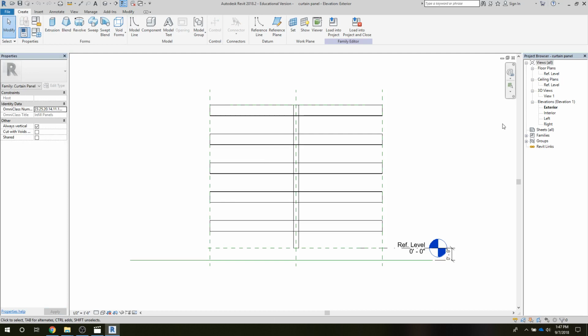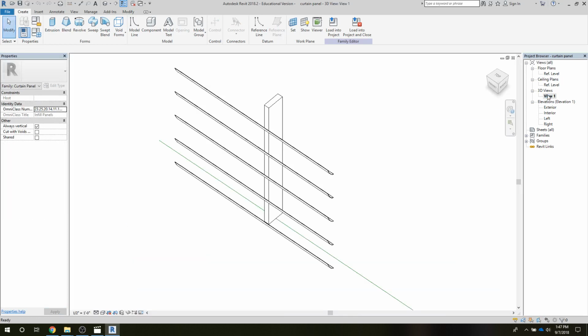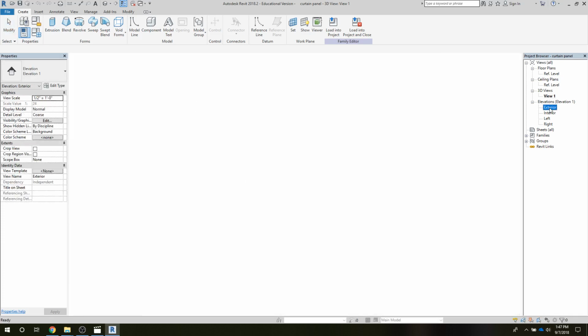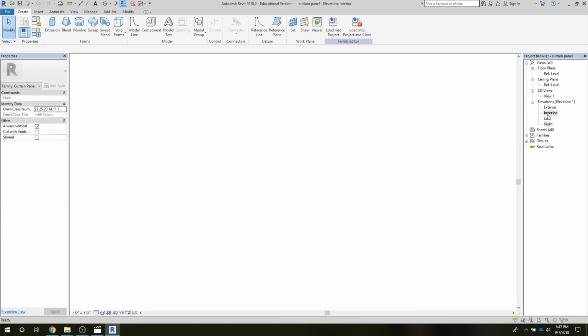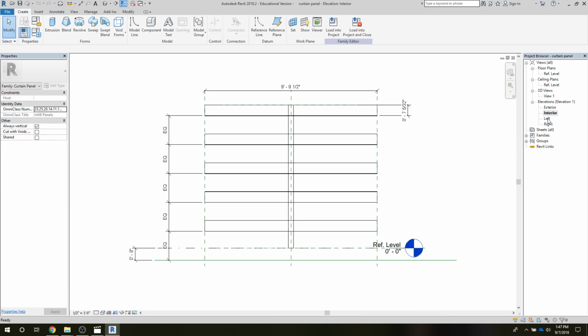So it's built up as a curtain panel, and that's a little bit screwy because it has a vertical orientation to it. So that causes a little bit of confusion at the start. So these louvers, though, are equally spaced. I didn't try to do an exact match. All I did was create 3, 4, 5 louvers in the system. And then I just took the last equal spacing and offset it so that the repeat would be even. So I'm assuming it's about 8 inches. So I set the offset for that and then took about half that distance.